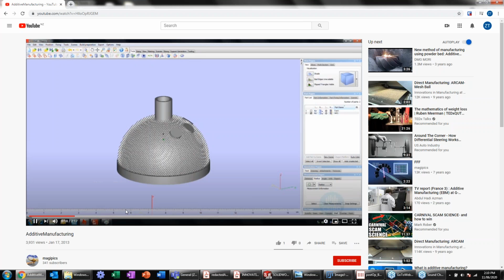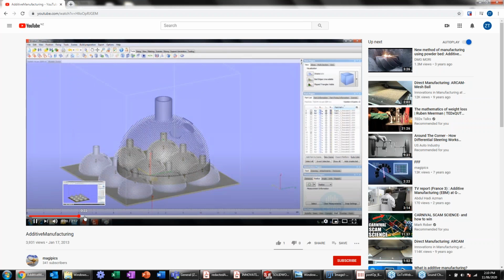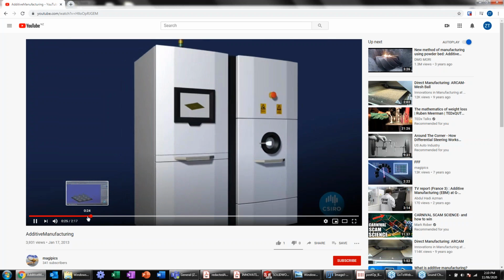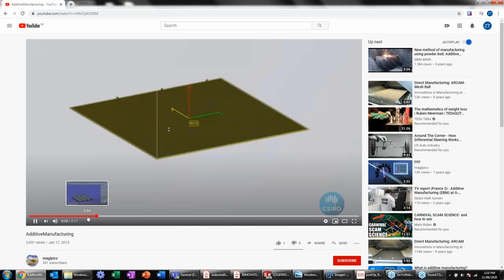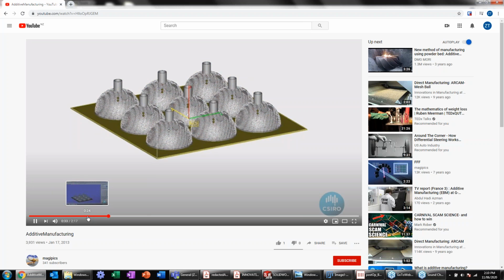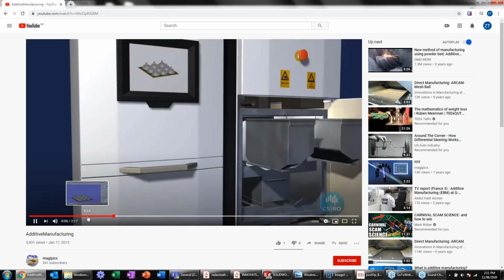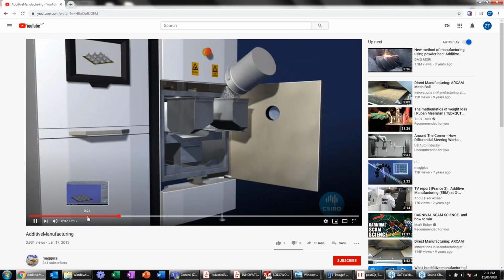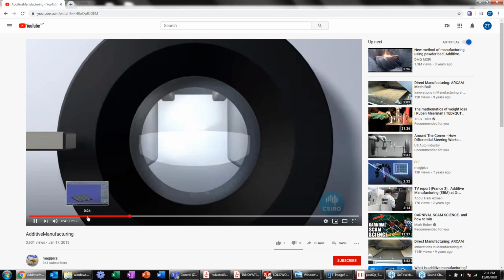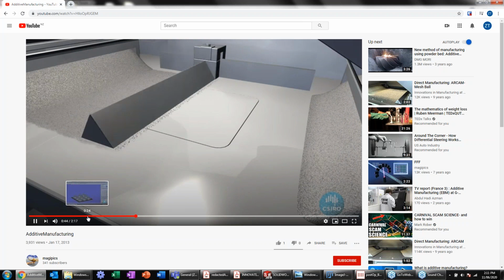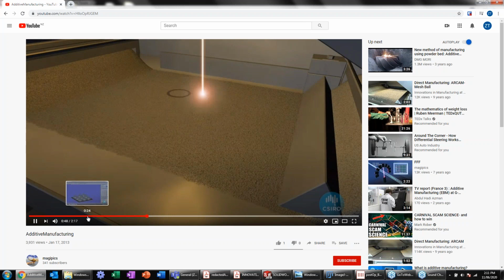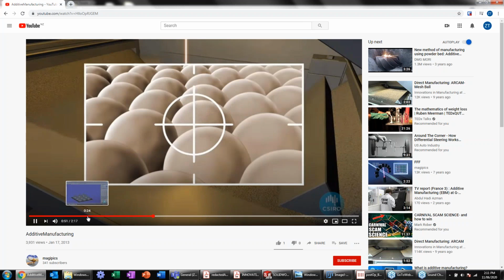So let's quickly watch this. Let's assume we've done all the CAD, we've got all the parts, and we're going to put them on the machine. So it's a powder bed based method, and we are building slices of parts or layers of parts. The machine has 2 hoppers, gravity fed onto a powder bed inside a vacuum chamber, and a rake will move the powder onto the bed. We preheat all of the powder and sinter it, and then we mount the layers of the parts.